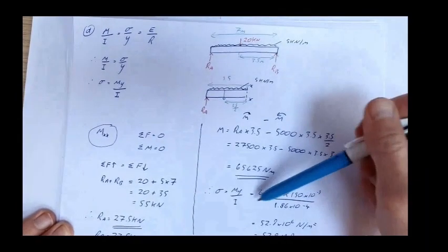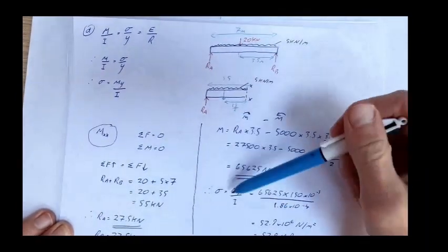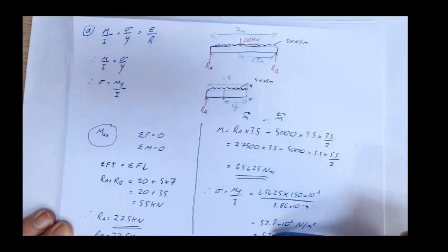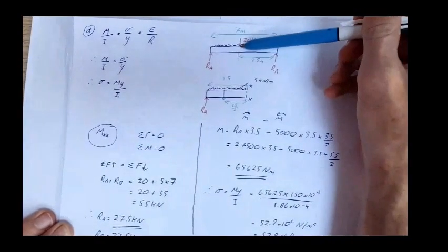And I we've got for this section. So my stress is 52.9 megapascals. That's actually going to be on the top surface of the beam, and it's going to be compressive, and it's going to be in the center of that beam.